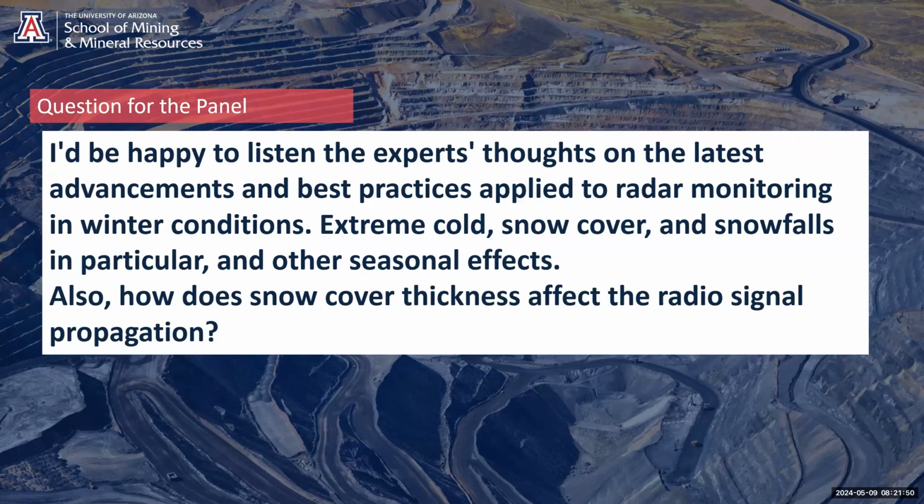Depending on the radar technology that you are using, you have the possibility of looking at the coherence parameter, coherence maps, coherence plots. So when I'm personally looking at data from mines covered with snow, I try to find areas or pixels that have retained high coherence even during the storm, during the snow events.